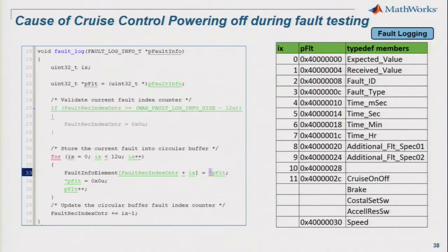So Chuck, if I visually inspect this, and I know the memory location of where the fault record resides, and I walk through, as you can see, index 0 to 10, everything is valid. Okay. However, when I step into index 11, it's actually overwriting the next memory location. Okay. So it looks like your stuff is writing over that.